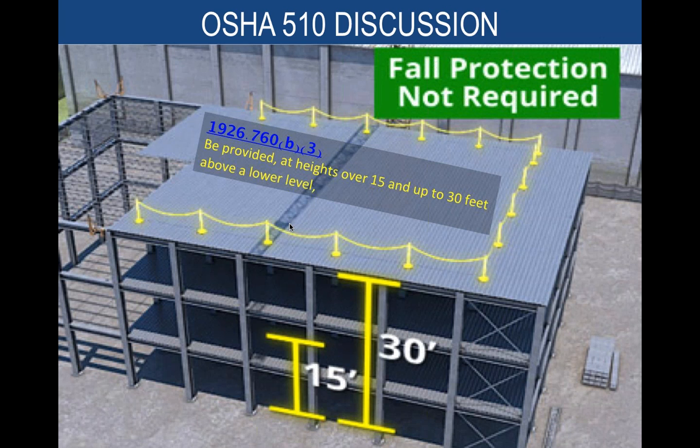We also have to comply with OSHA requirements for head and foot protection and hard hat zones. We have to locate and observe all warning and accident prevention signs and confine movements only to those work areas, right? So all the signs are going to have to be visible and accessible to employees. Also, we have to only enter restricted areas with permission from the superintendent or the foreman. So we have to be authorized if we're going to be within that fall protective area.